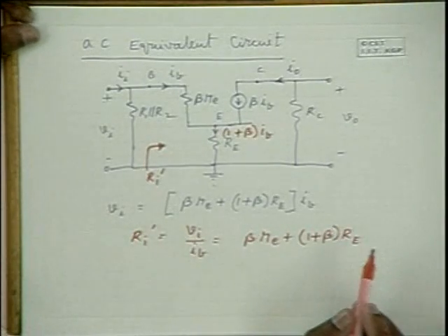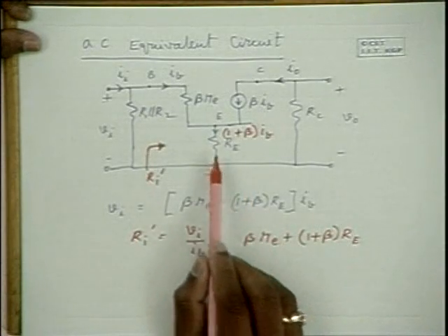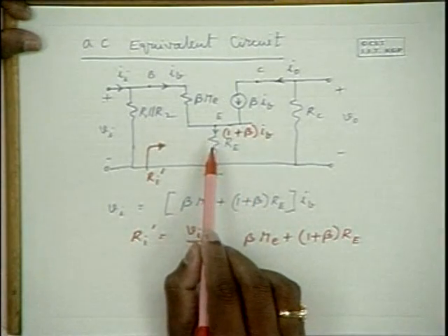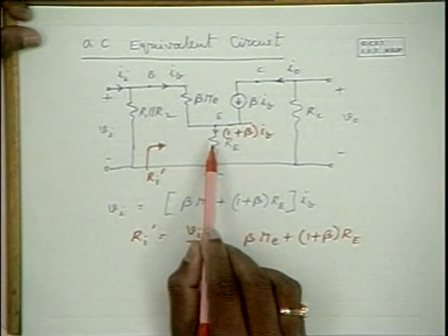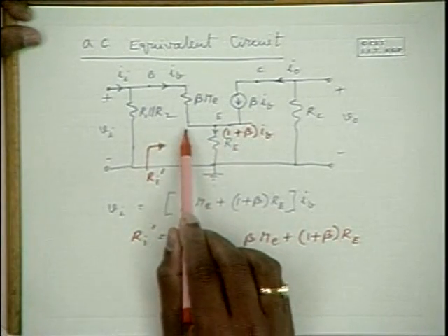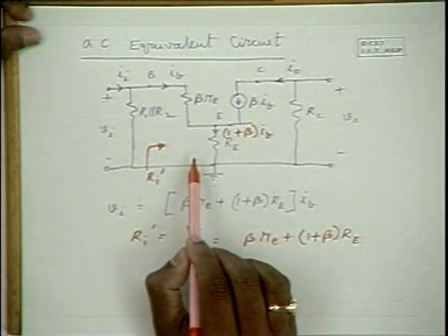Therefore, introducing RE here is like introducing RE into 1 plus beta as a resistance in series with this.